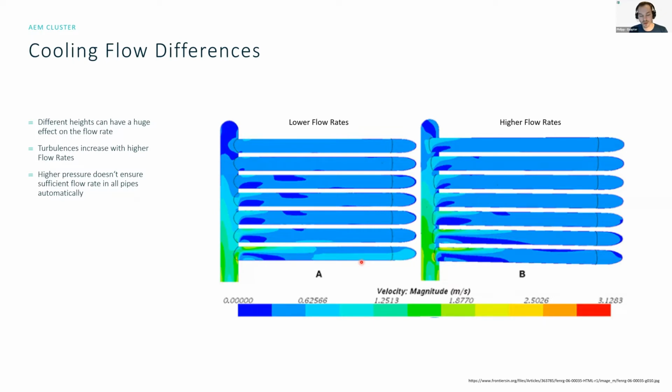When we imagine that we have several electrolyzers stacked on top of each other, and those electrolyzers are provided via the same pipe, which then splits up individually, then we can see that there are quite some differences in the flow rate depending on the position. The electrolyzers which are on the bottom of the cabinet receive a higher flow rate than the ones on the top.